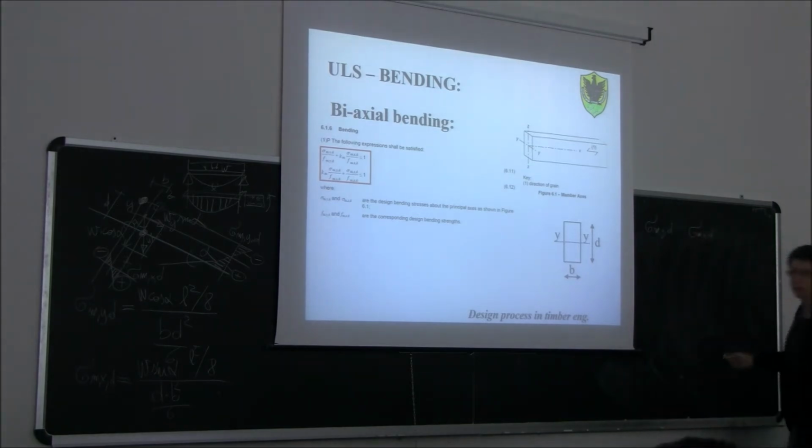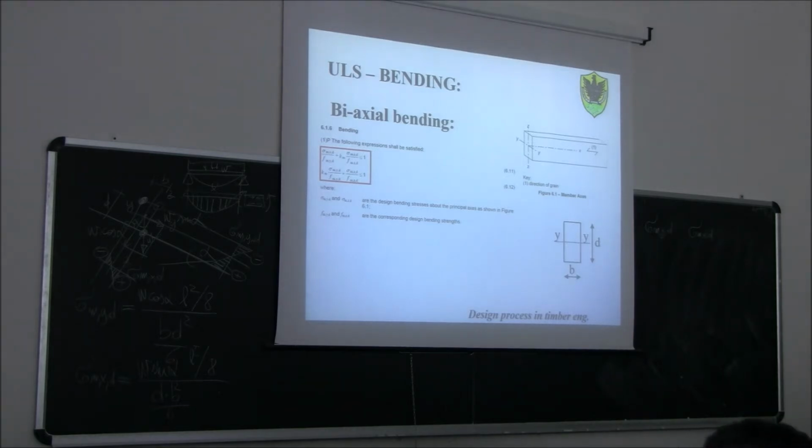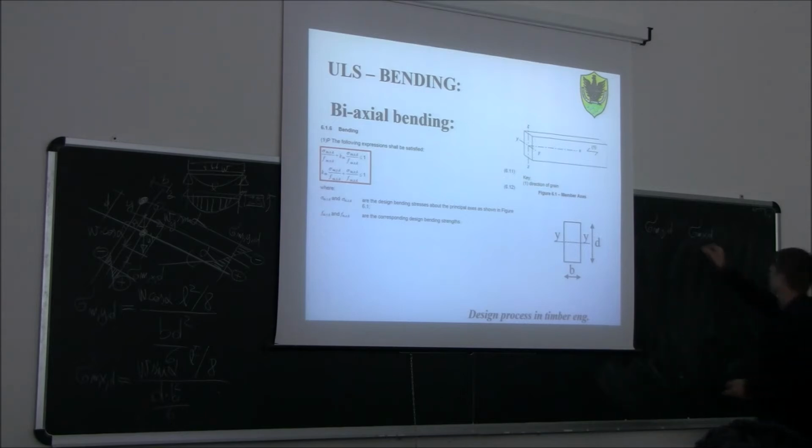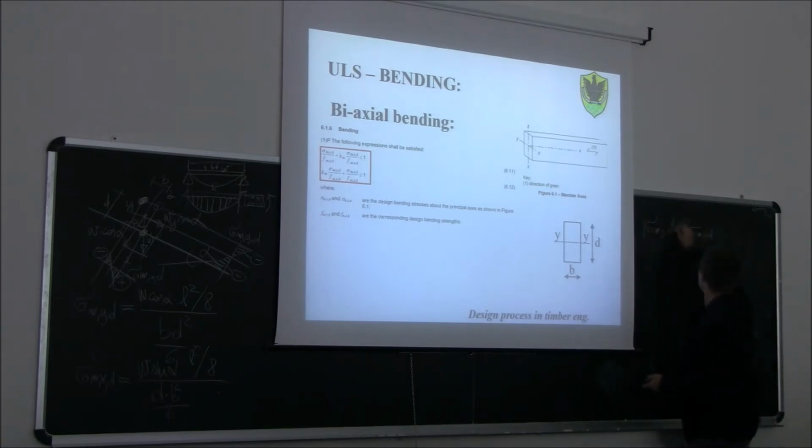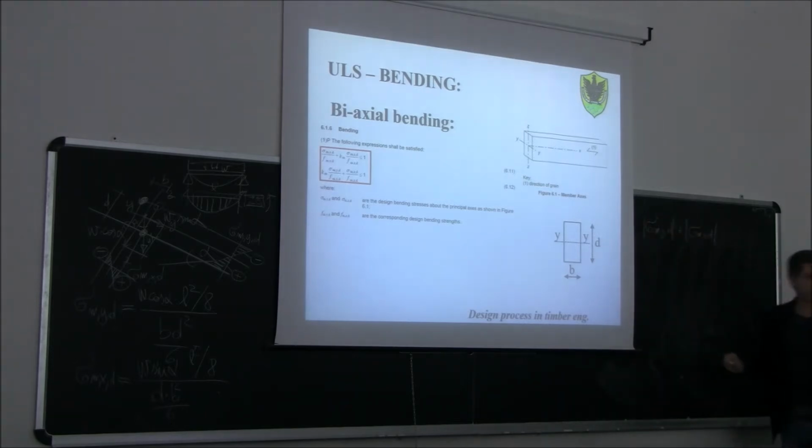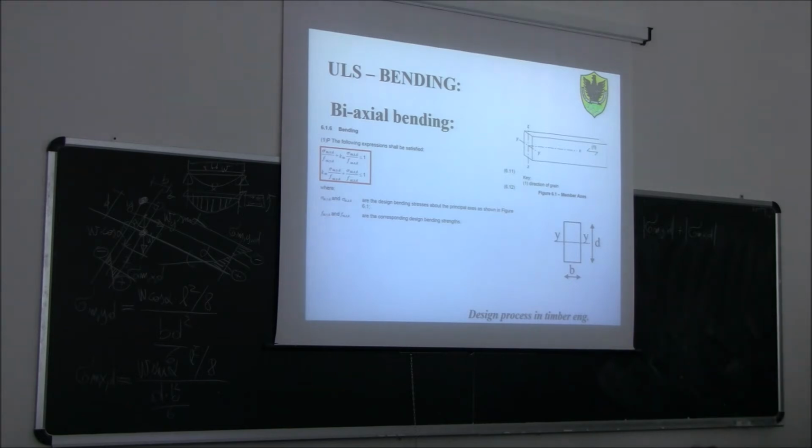What do I do now with these two values? We sum them up because we said that we have to superimpose here. They are all oriented in the same direction. Now we're talking about sigma, they are all parallel in the cross section. So we need to sum them up. If you want, we sum up with their absolute value, just not to have any problem.